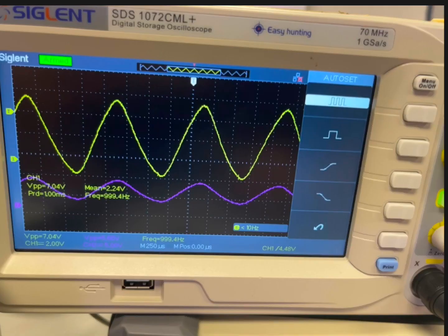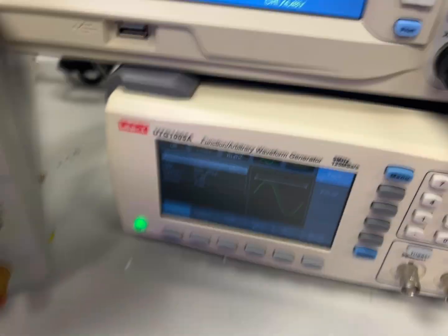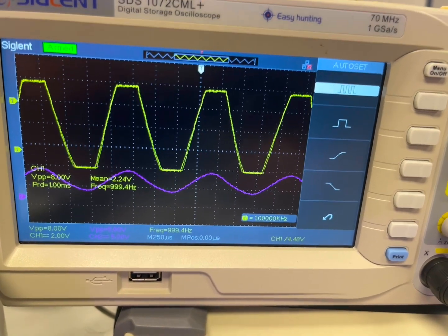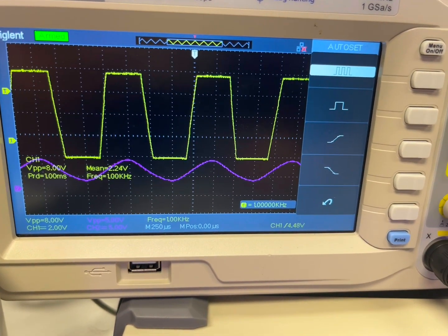To set up stage 4, we will place oscilloscope probes in both TP4 and TP5 and leave the power supply and function generator untouched. There, we can get a voltage output of 7.04 volts. By adjusting trimmer 2, we can control the output at TP5. The final output would then be the maximum sine wave without being saturated.